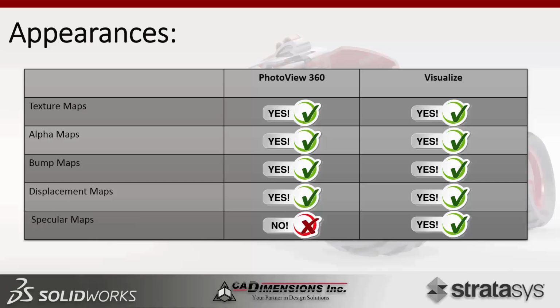Also on the topic of appearances, we have a bunch of maps that we can apply. All of these would apply back and forth from PhotoView360. So you can apply texture maps, alpha maps, bump maps, displacement maps. The only one that PhotoView360, to my knowledge, does not support would be a specular map.